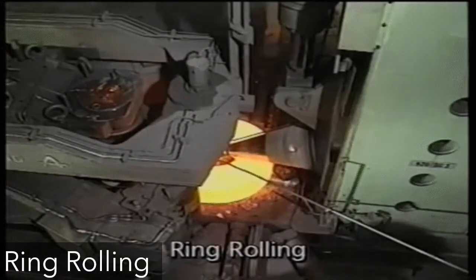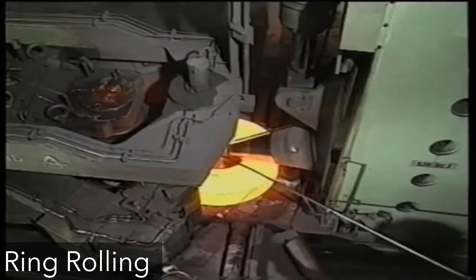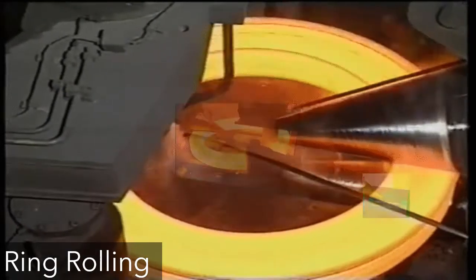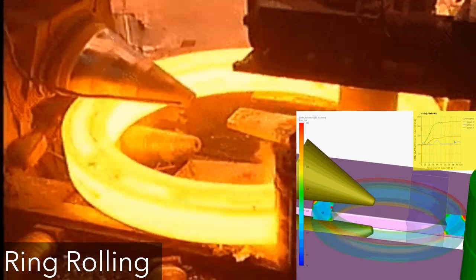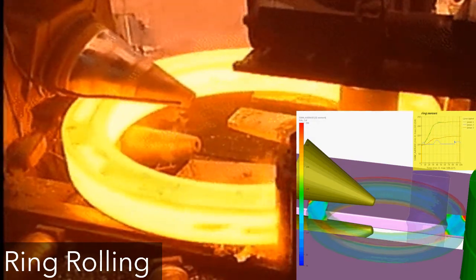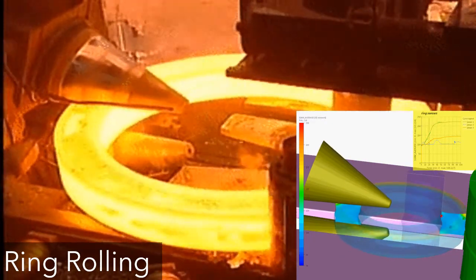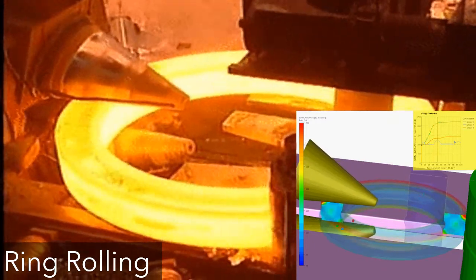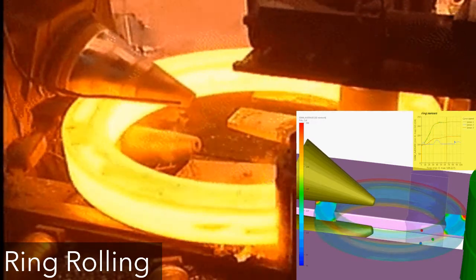Ring rolling is a deformation process in which a thick-walled ring of a small diameter is rolled into a thin-walled ring of a larger diameter. As the thick-walled ring is compressed, the formed metal elongates, causing the diameter to enlarge. The hot working process is used for large rings and the cold working process for smaller rings. The products include ball and roller bearing races, steel tires for railroad wheels, and rings for pipes. Also, pressure vessels and rotating machinery parts.